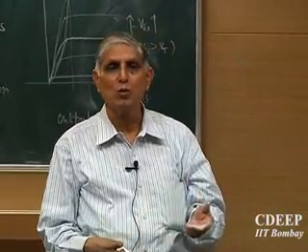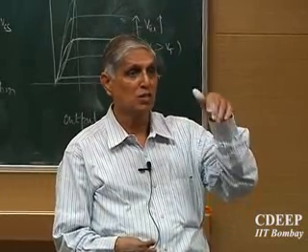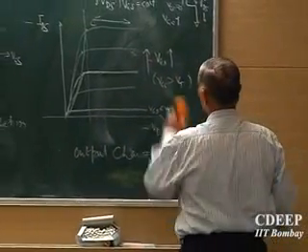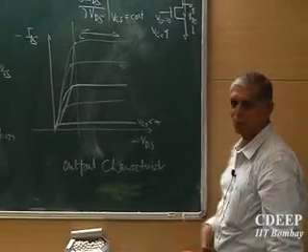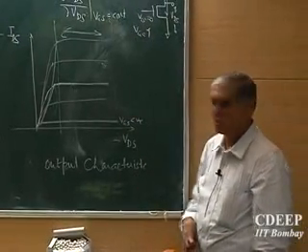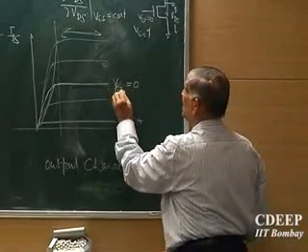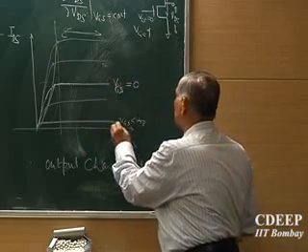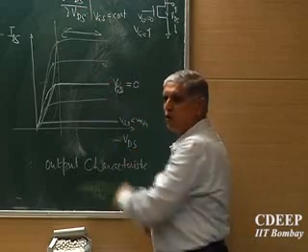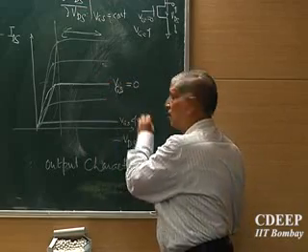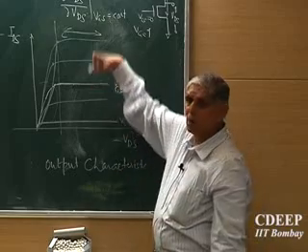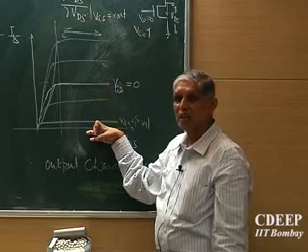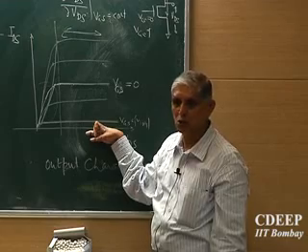We will use only enhancement mode, but there are circuits which will use depletion transistors. In the output, let's say it looks similar, but what should I change here to make it look like a depletion transistor, N channel at least? Somewhere here, VGS is 0, it's conducting. Below that it will reduce, somewhere here it is VTN. When it goes to this negative value, then it will be switched off finally. Above that it will act like an enhancement mode. Below that it will actually deplete out and current will go to 0, and it will require a minus value of threshold to turn it off.